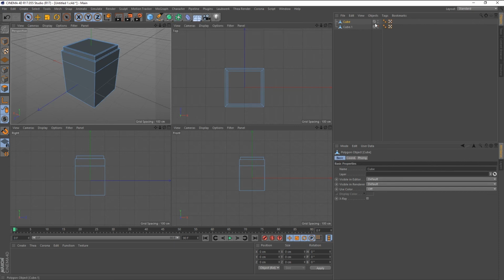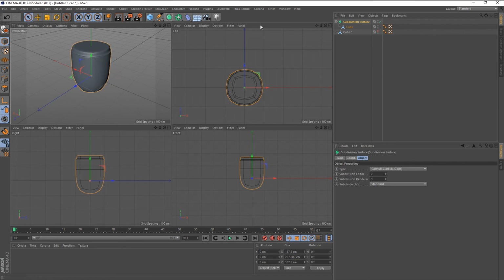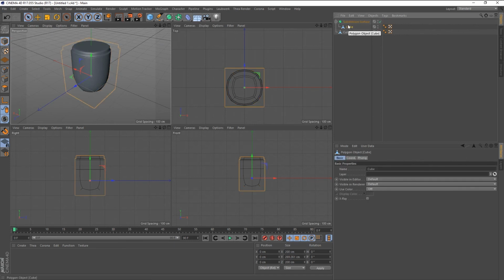They're in here. So if I have an object, let's go back into object mode. I'm going to click on this, modeling mode, what Blender would call object mode. If I'm in modeling mode and I hold the Alt key down and I click on subdivision surface modifier, it will add the subdivision surface modifier to my cube. If I click on this little check mark, I can hide that modifier. I can temporarily disable that modifier while I'm working on it.